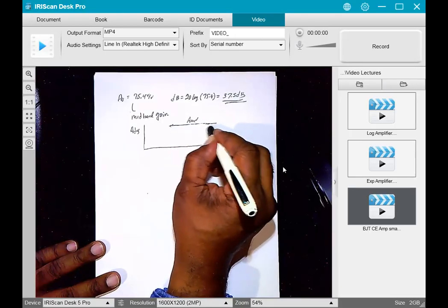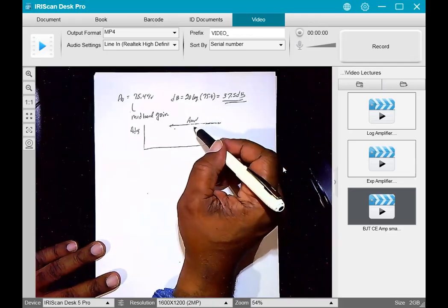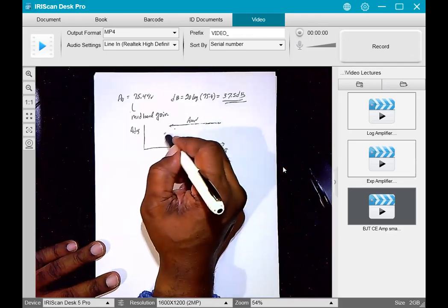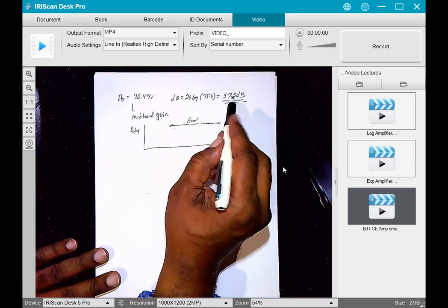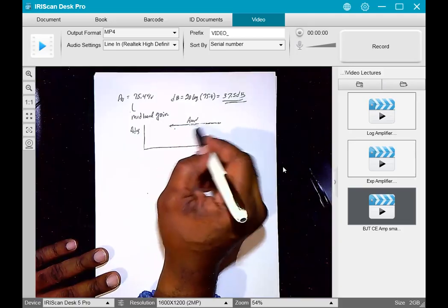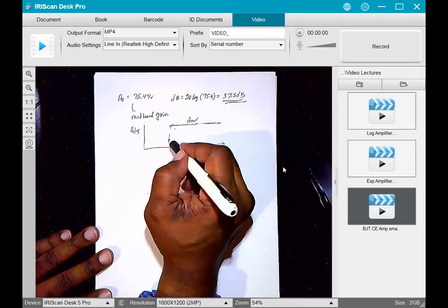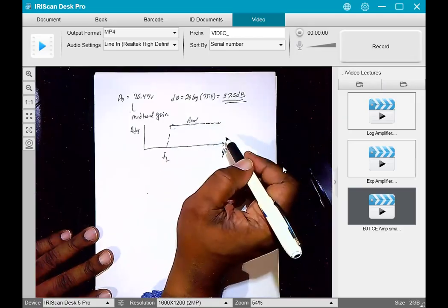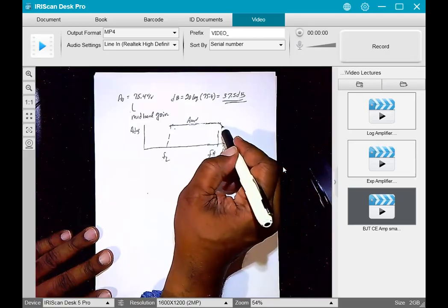Our gain is not going to change a whole lot when we calculate it in dB. Now it's actually changing, it's not staying flat. But when you convert it to dB, you don't see a whole lot of change. It's going to look relatively flat until you get to your pole frequency here and your pole frequency here. And then it'll start dropping off.